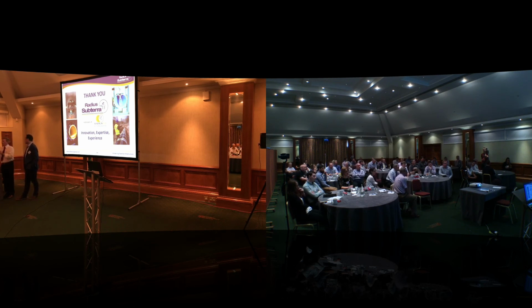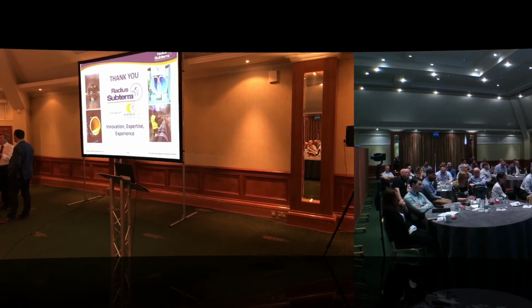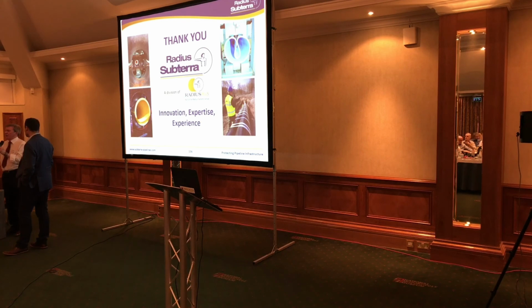The roll down system, after the roll down process, there is a slight amount of recovery, but it stabilises at a stable diameter. As I said in the presentation, it's extruded in the factory at DN155, but it comes to site as a DN144, I think it is, and it remains stable at that size. We've actually checked the dimensions of liner pipe on drums as part of this technology demonstrator, and lo and behold, it stays down, so it's very good from that point of view.